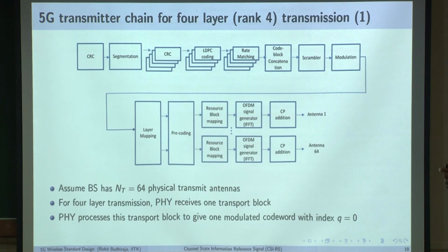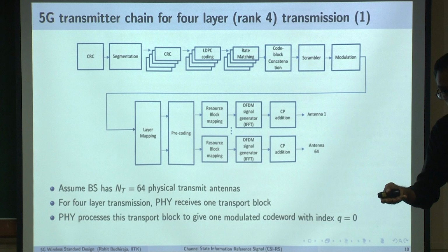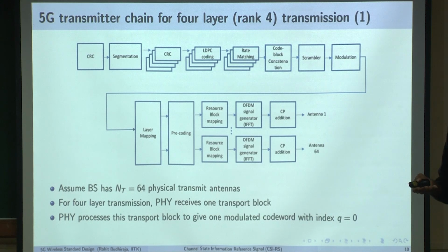If you remember the way the transport block size was calculated, the number of layers also plays a role. If the number of layers is 1 and the number of resource blocks is, let us say, 10, the transport block size, just for example, is 100. Compared with that, for NL equal to 4, MAC will send a transport block size of 400, even though it is over the same 10 PRBs.